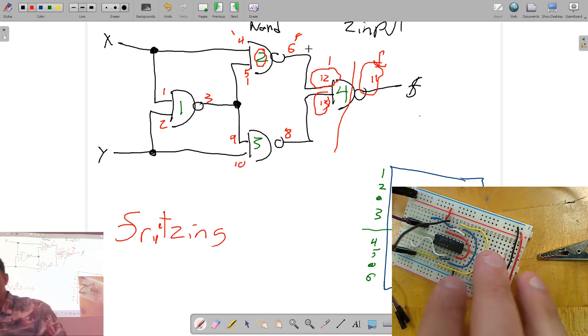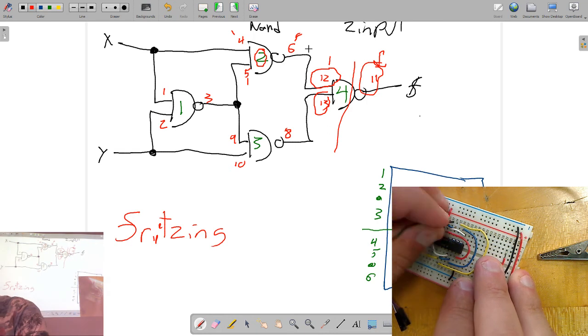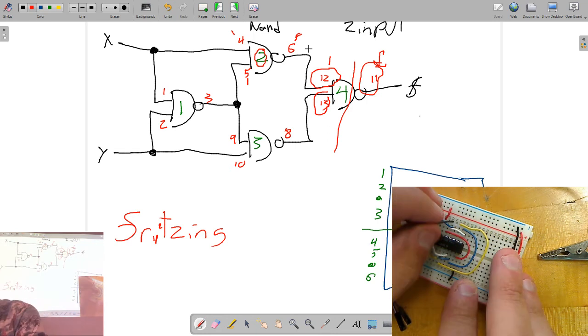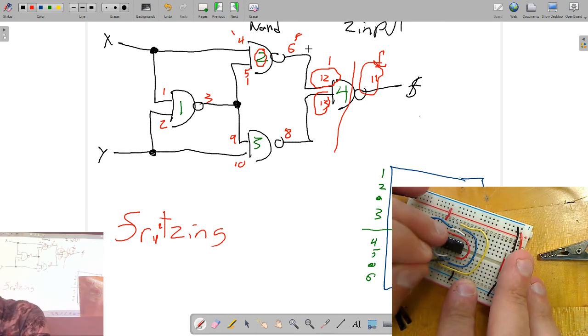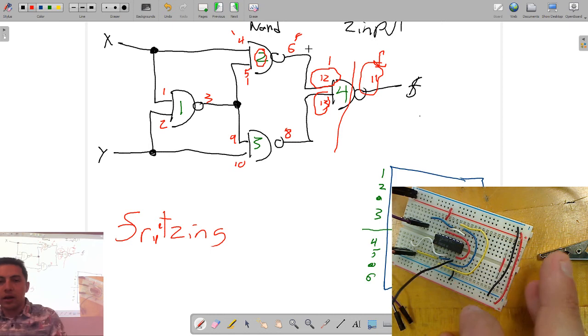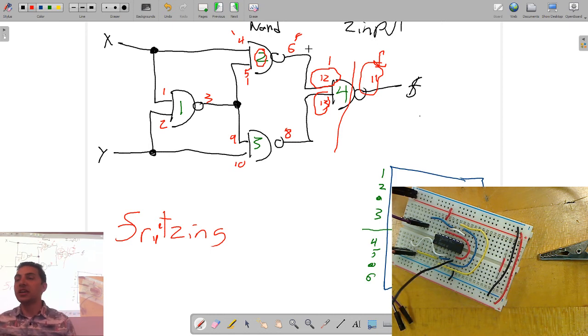So what I'm going to do now is, instead of being on pin 12, I'm going to go and look at pin 6. Now, there are 2 options. Either 6 is correct or 6 is wrong. Now, if 6 is correct and 12 is wrong, that is diagnostically very important because they're supposed to be the same. So why would they be different?